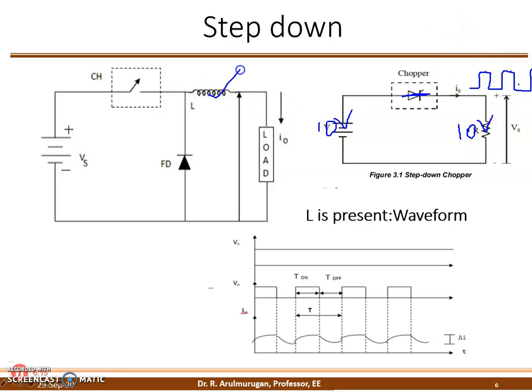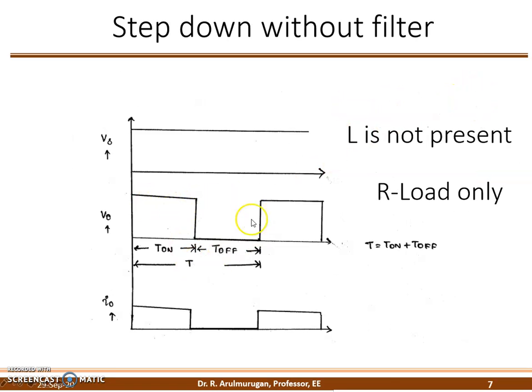Suppose I use an inductance, either here or as an RL load. What is the response? First, understand the circuit here. I use neither an RL load nor an inductance, only a switch. So this is the waveform. The output voltage and output current, for an R load, are both similar, and the waveform is of the pulsating type: on, off, on, off. The output current is pulsating DC.